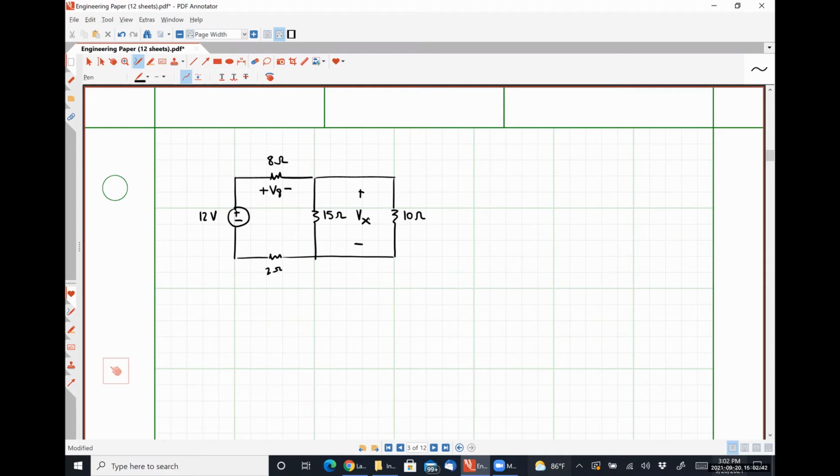That's exactly right. That's all you need to do. Just combine those two parallel resistors into a single equivalent resistance. And now this thing is a voltage source connected in series with a bunch of resistors, and voltage division is fair play. You will get to a point, I hope, to where you won't actually need to do that combination itself. You can just add that into your equation. So what I mean by that is you could take the steps required to actually simplify your circuit.